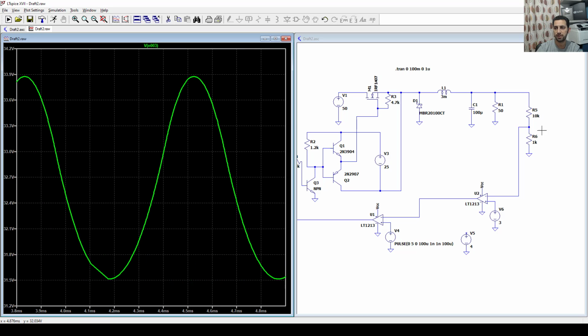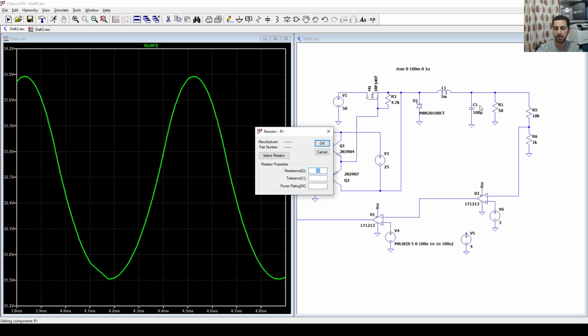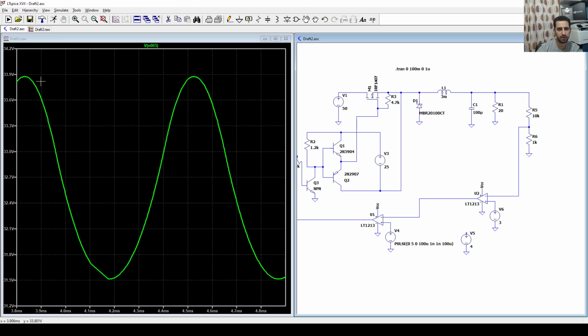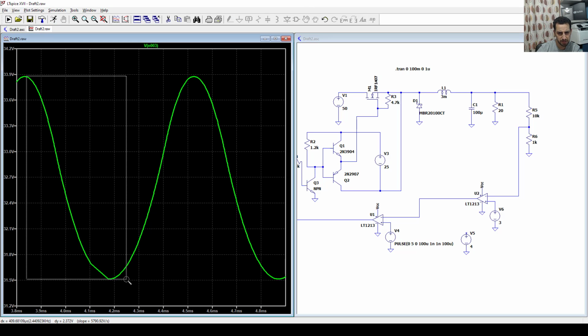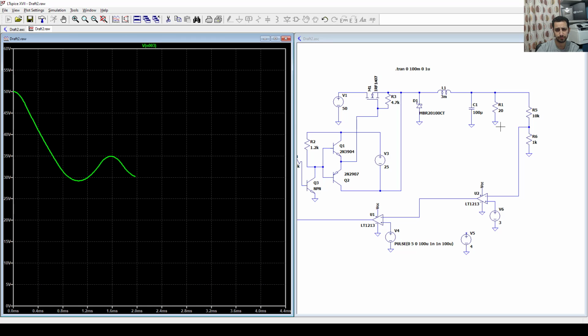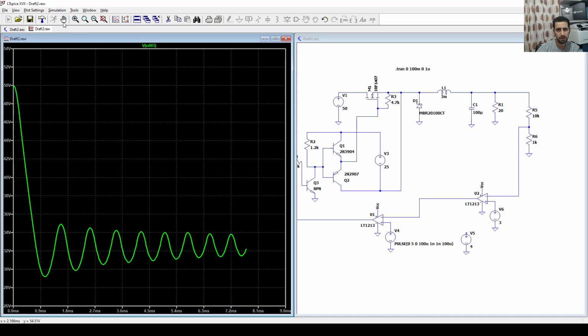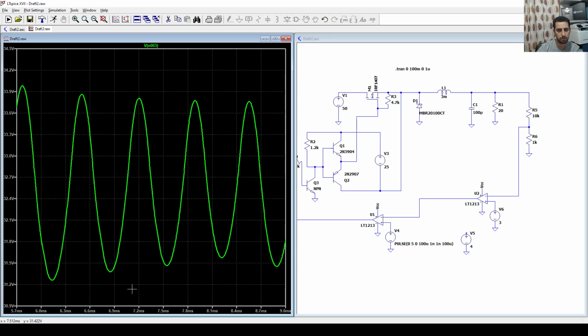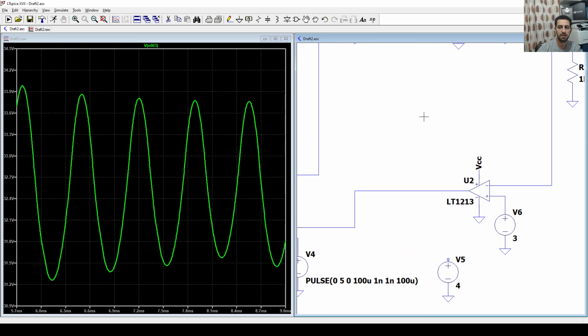Sometimes it's small. Okay, if I change my load here, so for example it's not 50, it's 20. I think that the ripple now from top to bottom is about 2.3 volt in this bar here. Now if I want to run it with a higher load, it will be more ripple. Yeah, it's damping but still more ripple, and oscillating for a longer time, so it's still not very adequate for my control, and maybe I can enhance it.